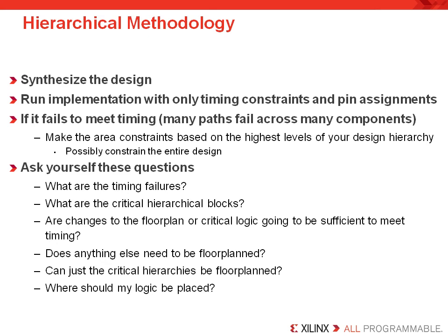When you create a floor plan for your design, try to ask yourself the following. What are the timing failures in my design? Then what are the critical hierarchical blocks? And are these changes to the floor plan or critical logic going to be sufficient to meet timing? Or do I need to floor plan anything else? Can I just floor plan my critical hierarchy? And where should my logic be placed?